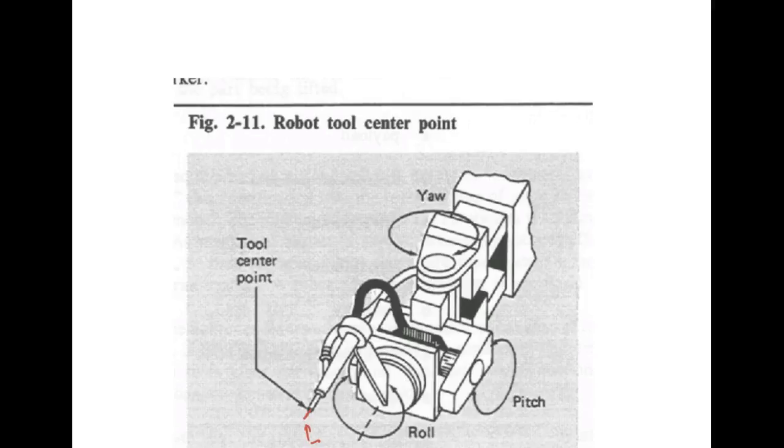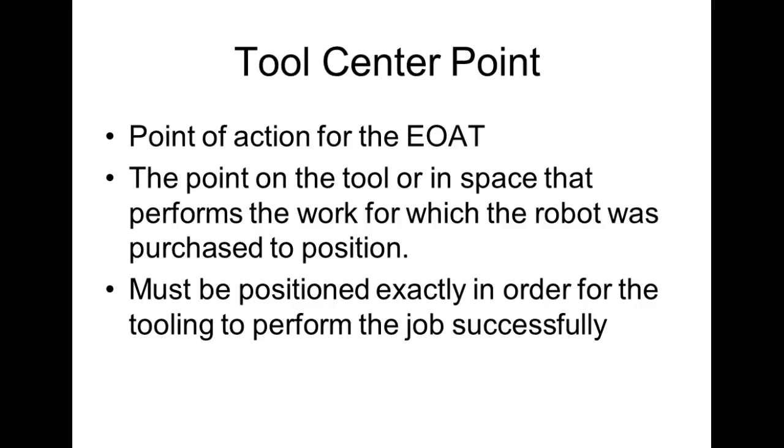They don't put power on it, they use it as a touch sensor. But those robots, before they use it, will swing around, feed wire out, and have a clipper that clips it to an exact length. Once it's at an exact length, we can use that to measure stuff, which is pretty neat. So what is the tool center point?